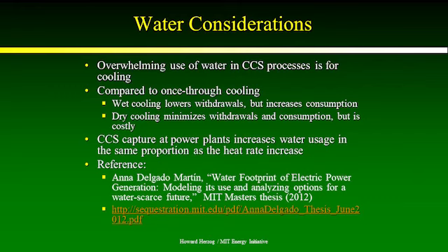And so let me just wrap up and just say that once again, processes can differ, and the Climeworks process I talked about before actually can use no water and actually generates water. Why is that? Because they put lots of air through the system, so they use air cooling instead of water cooling for the waste heat. And secondly, when they use their amine absorbent, it actually captures CO2 out of the air, 2 molecules of water for every molecule of CO2. So that could actually generate water. I'll stop there and welcome questions.